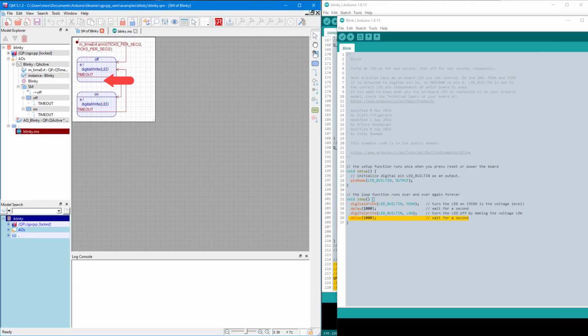This is because you never wait for events inline, so your software remains responsive to any new events. You can think of the QP framework as an operating system, or more precisely, a real-time kernel, that can manage many active objects simultaneously and can easily handle thousands of events per second, not just 2 timeout events per second like in the simplistic Blinky example.